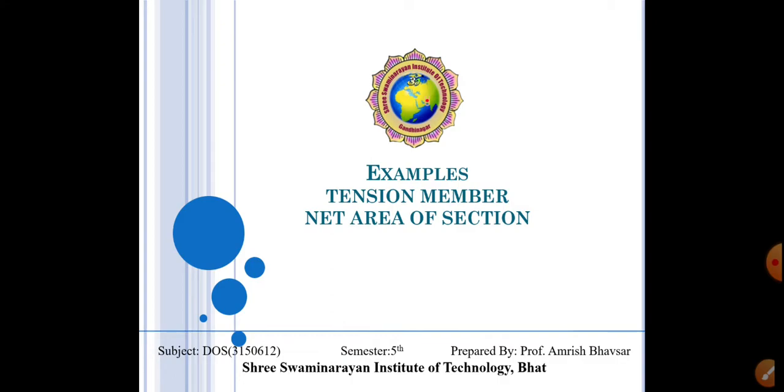From these three capacities, we consider the smallest one of them, which is known as the design tension capacity of the member, that is called TD. So now, in the equation of rupture, you can see that equation on page number 32 in IS 800 2007.